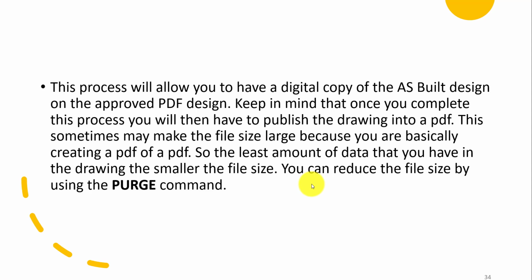Again, this process will allow you to have a digital copy of the as-built design on the approved PDF design. Just have to keep in mind that once you complete this process, you will then have to publish the drawing into PDF, as I stated earlier. This sometimes may make the file size large because you're basically creating a PDF of a PDF. So the less data that you have in the drawing, the smaller the file size. And you can reduce the file size by using the Purge command.